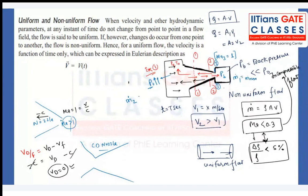Now tell me, will this m2 be less than the maximum mass flow rate which we achieved earlier, or more than the maximum mass flow rate? Definitely mass flow rate will increase if I increase my inlet pressure. That is a function. When you see the maximum mass flow rate formula, you will come to know that it is a function of P naught.